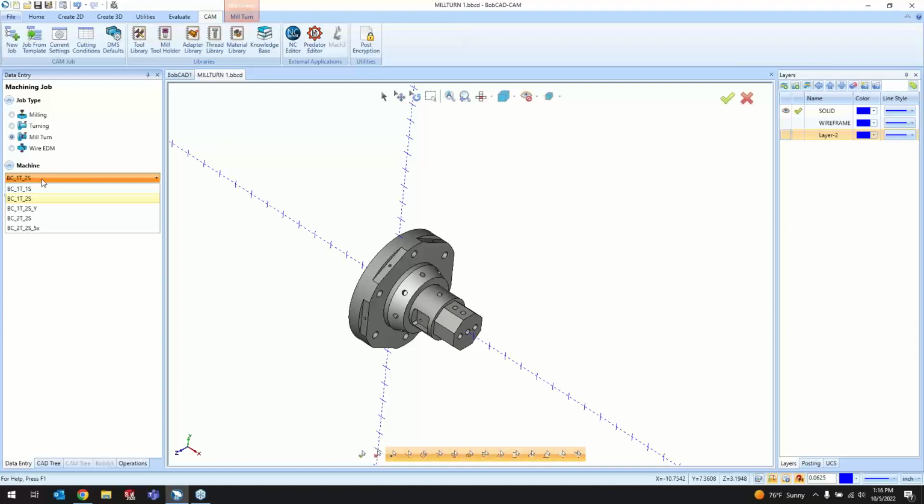And if you have a Haas or any other type of machine that you're using, we do require a post request where we give you a worksheet to fill out, letting us know the axes of rotation, whether it's a 4 or 5 axis mill turn machine, how many turrets, how many spindles, and the limits to each axis as well, to make sure that there's not going to be any over travel, and the kinematics of the machine to make sure that there's not going to be any collisions with any of the tools on the turrets and anything else with the machine involved there.